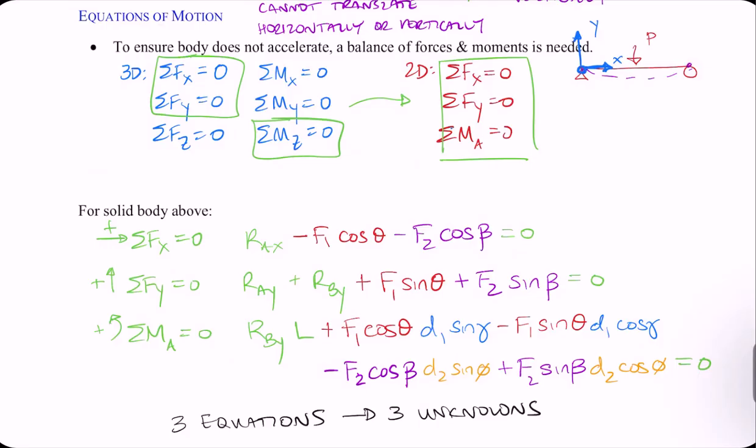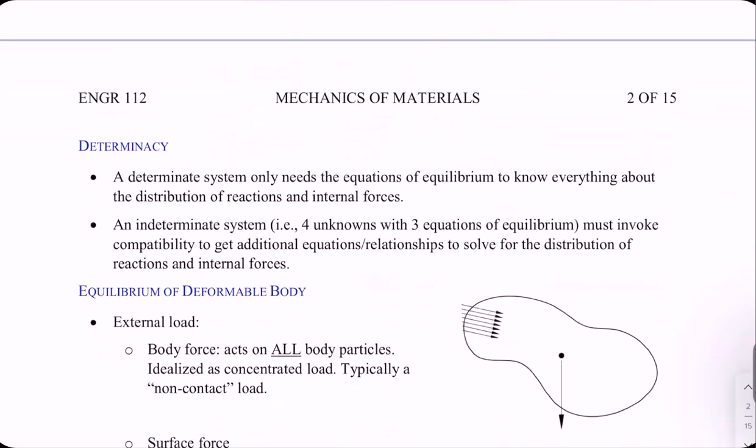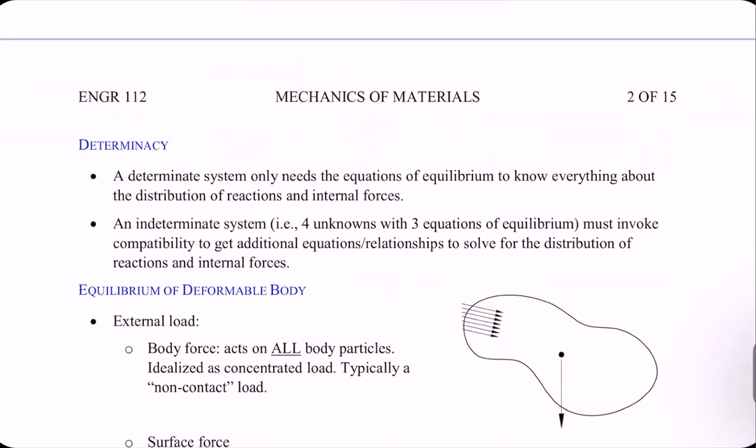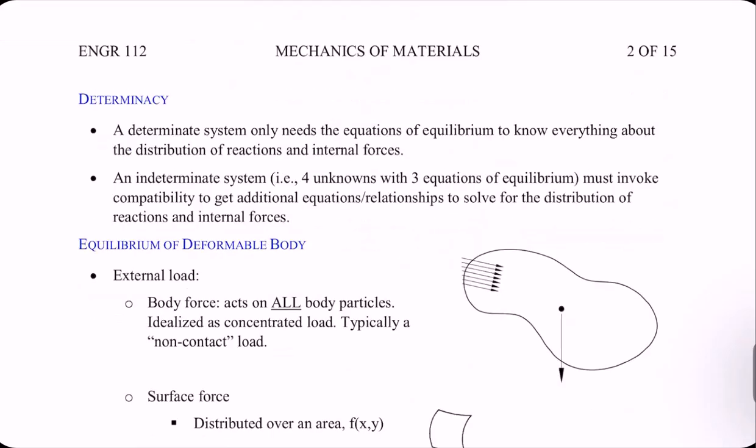It can get pretty tricky with all of our angles, but ultimately we're just breaking everything into our x and y components, adding the x together, adding the y together, making sure when we do our moment arms we are using the perpendicular distance to the force. So this is all well and good when we have determinate systems. This is primarily what we'll be dealing with in this course. We will see some indeterminacy, but all that means if we have a determinate system, just those equations of equilibrium will help us find reactions, which will lead us to our internal forces.